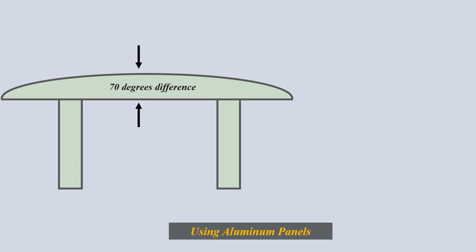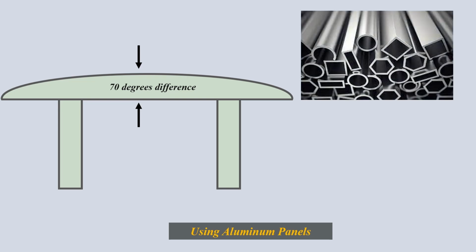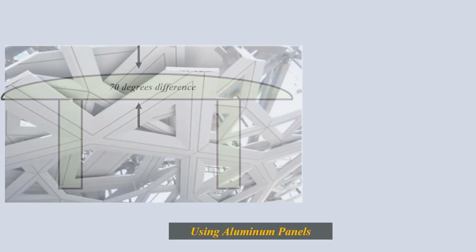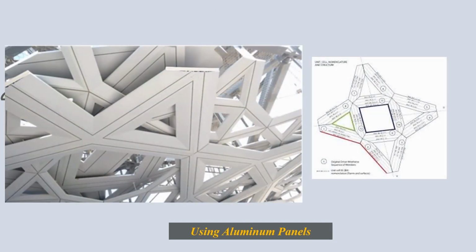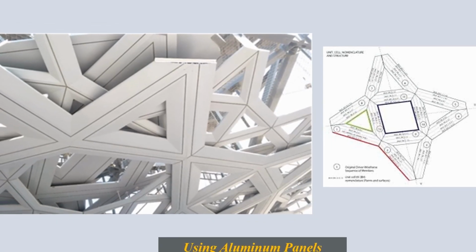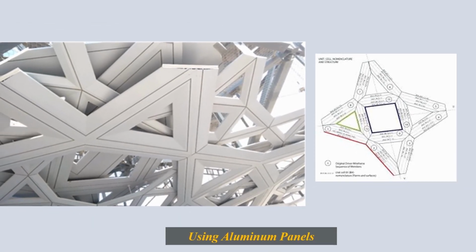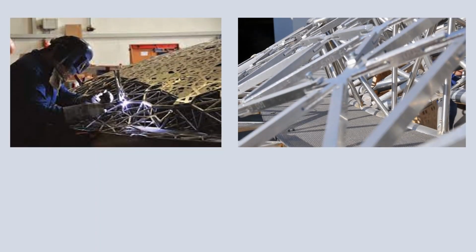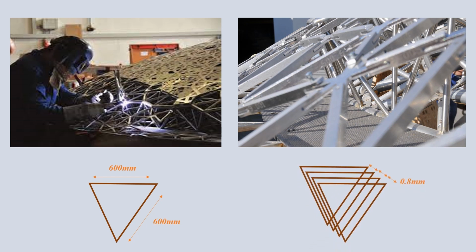Due to the thermal expansion of the structure, the only solution available for dome cladding was to apply aluminum ALMG3 and H111, which is the same material that was applied to the actual structure. The cladding was built with a small module of approximately 600 by 600 mm and assembled at intervals of 0.8 mm each for thermal expansion.